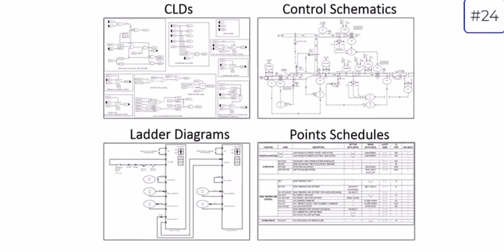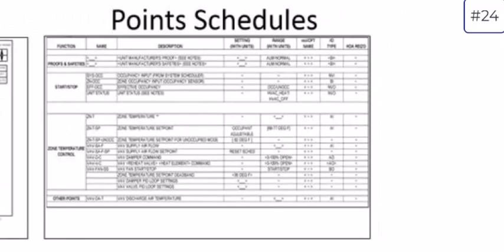An exception for that is the point schedule. So here, per our unified facility criteria and specifications, we want to have a lot of information that indicates the controller ID, based on the protocol in use, if there's BACnet object types that we want to make sure are recorded, if there's any specific routing that has a protocol component to it, if there's Niagara IDs, we want to make sure that all of that is contained in a document that can pass from your building level controller to your UMCS integrator.